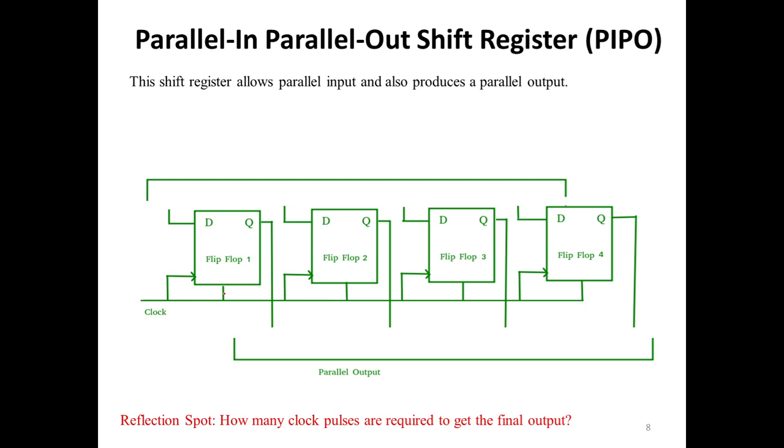So students, again here the clock is common. Can you think how many clock pulses are required to get the final output? Yes, within a single clock pulse, all flip-flops will work together and give the output because it is a parallel in and parallel out shift register.